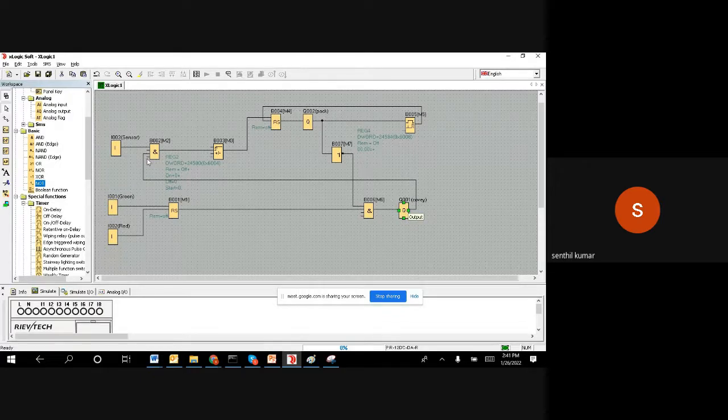Okay. When my conveyor is running, my sensor is sensing. The conveyor should be running in order to sense with the sensor, because we want to take real bottle movement, not false. This I did not tell, but if you do not have it, it's not a problem. But I'm telling you just to make foolproof programming. The program is supposed to be full-fledged, fully functional, without loopholes, and it should work even if the operator may not be telling some problems, but we need to think of all the problems and we have to implement, right?